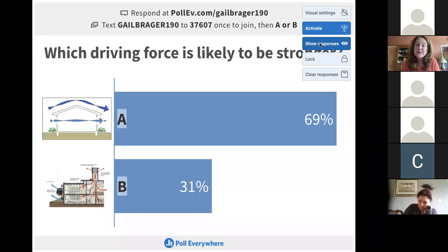But you have a lot of circumstances where the wind isn't available. So when people are designing for natural ventilation, often what I've heard engineers talk to me about is that they first design the building so that it operates well with stack ventilation. So they imagine the worst case scenario when there might not be any wind available. And in those circumstances, is the ventilation still going to work? And then if it works for stack ventilation, as soon as there's wind, it's likely going to work even better.